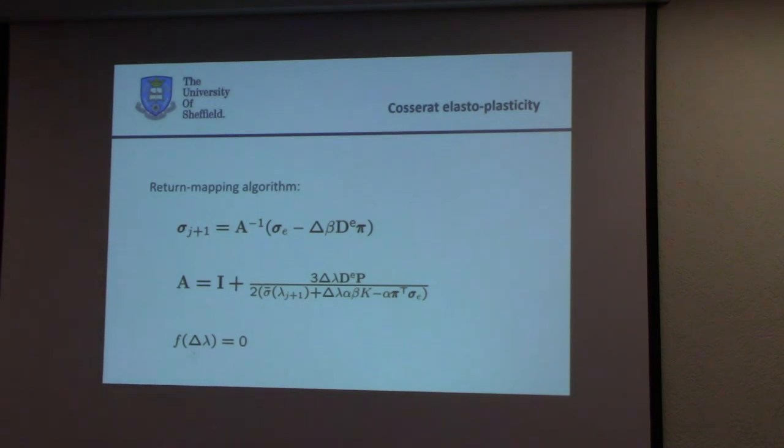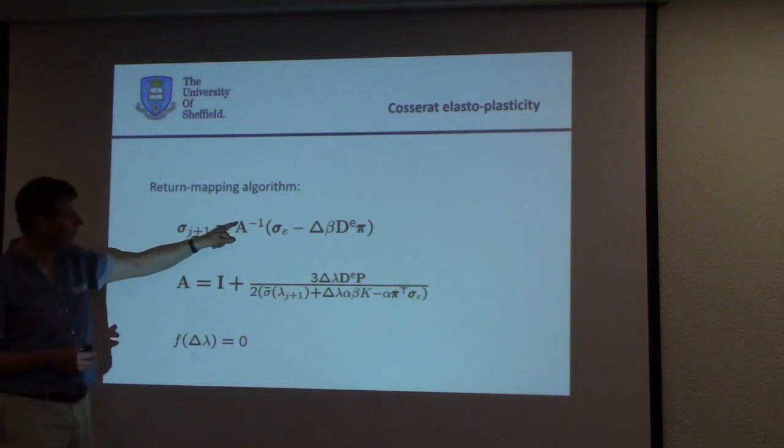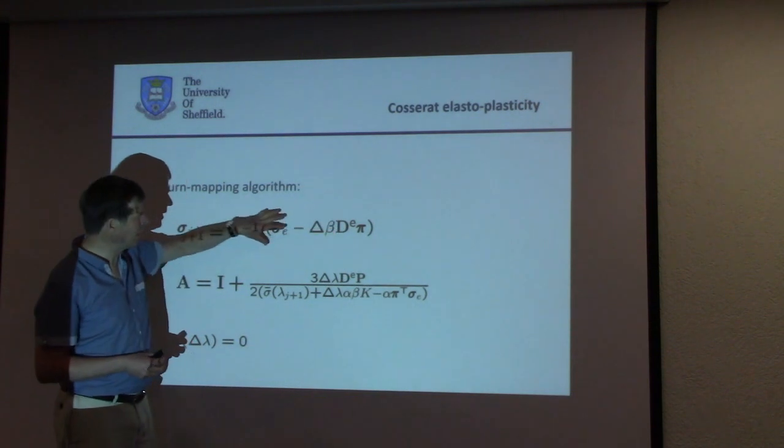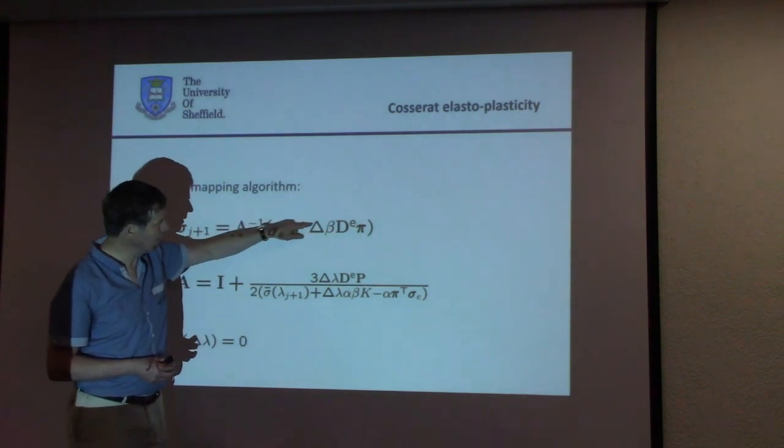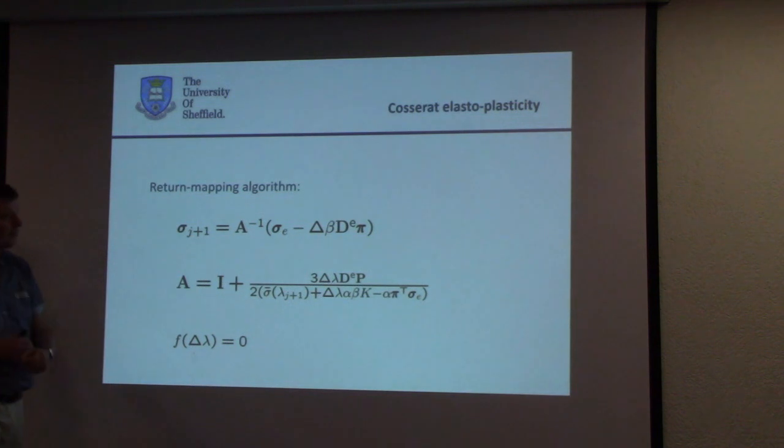Sometimes in the old literature, you see still the expression between the stress rate and the strain rate. That's wrong, because if you differentiate these, you again have to first differentiate this part times this, and then the other part times this thing, times this delta. And that gives an additional term. And this additional term is crucial for obtaining rapid convergence.